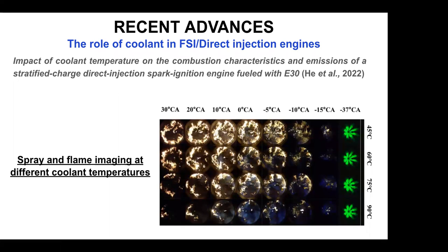From the optical results as shown in this figure, at lower coolant temperature, the flame has a higher brightness and larger areas of white-yellow sooting flames, indicating that more soot particles are generated due to larger rich combustion zones.